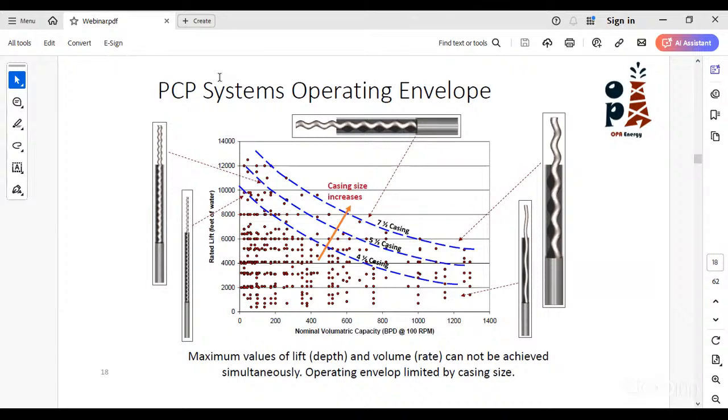But finally, we have stages, not a normal impeller and diffuser as in the ESP, but a stator and a rotor inside the ESPCP. So you can handle much more sand content, much more gas rate, but you are deploying a cable to the system and you are running a motor from below, not from the surface equipment that we have in the PCP. So the ESPCP combines the good things from both artificial lift systems.